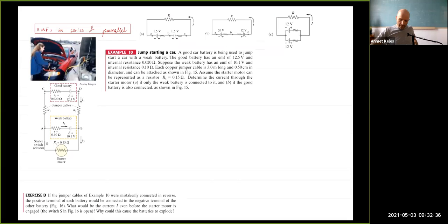For example, we can put one battery after another. Maybe you would like to have a higher voltage, so that makes sense, right? And then you have a higher current passing through R. But you could actually connect these in opposite ways too. You may say, look, why would I do that? Actually, you do this all the time whenever you charge your phone. Not exactly this, but something like this. You connect the battery in your phone in the reverse direction of the current so that it can be charged. For example, this 20-volt battery here is charging the 12-volt battery if this battery is rechargeable.